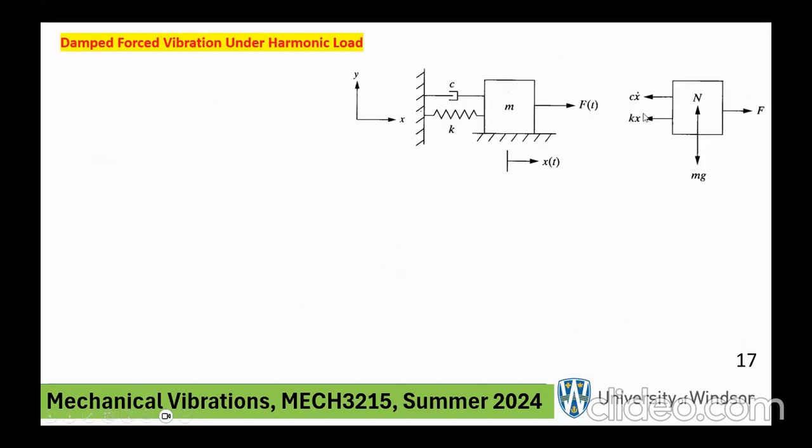There we are. Free body diagram. The only additional term is the damping force on the left side. So here's the mother of all equations. If you want to clean it up, write a different form, you can divide by m. If you divide it by m, k over m is omega n squared. Big F naught over m we call little f naught. And c over m became 2 zeta omega n. These things we have done in lecture 3 or lecture 4. All right.